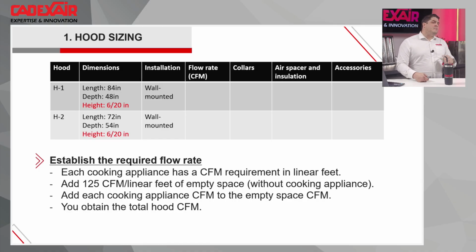We understand that we'll maybe exhaust a little bit more than others, but at the end of the day, we understand the energy efficiency is very important because kitchen exhaust hood systems take a lot of energy when you bring back the air you exhaust. But something I learned, the more you try to be on the exact value of airflow, sometimes you will be a little bit short, and when you're short, you will have problems.